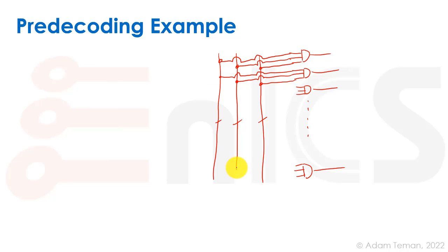Where do these buses come from? They are actually the outputs of decoders. So these are the predecoders. There are going to be 3 predecoders because we defined that the postdecoders are going to have a fan-in of 3. So we're going to have to tap one of the signals coming out of one decoder, another from the other decoder, and another from the other decoder.